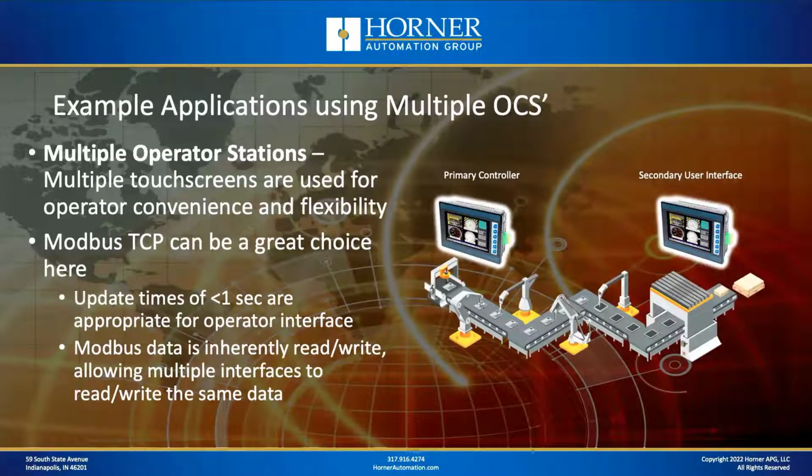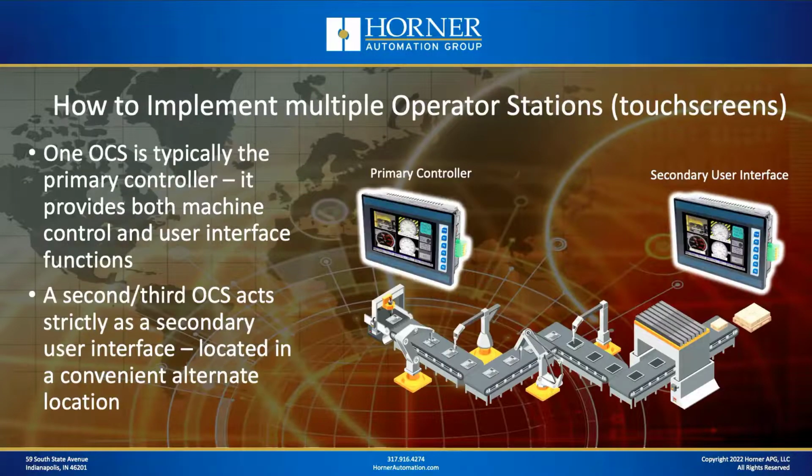With Modbus TCP, you can read and write the same data to the same registers. So the same registers can be read and written by multiple controllers. That makes it a really nice choice for this application. Now let's talk about the workflow, or how we would implement multiple operator stations in an application.